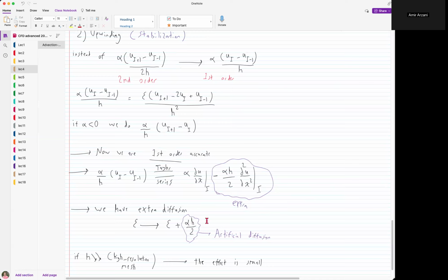And you can only show these things for one-dimensional cases. That motivates the whole finite element stabilization literature: a lot of times when we introduce stabilization parameters, they include some free parameter. So in this case, it's the artificial diffusion multiplied by some free parameter beta. Often we can study those free parameters in a simplified one-dimensional equation where we know things very well, derive things very easily, and find what they are.